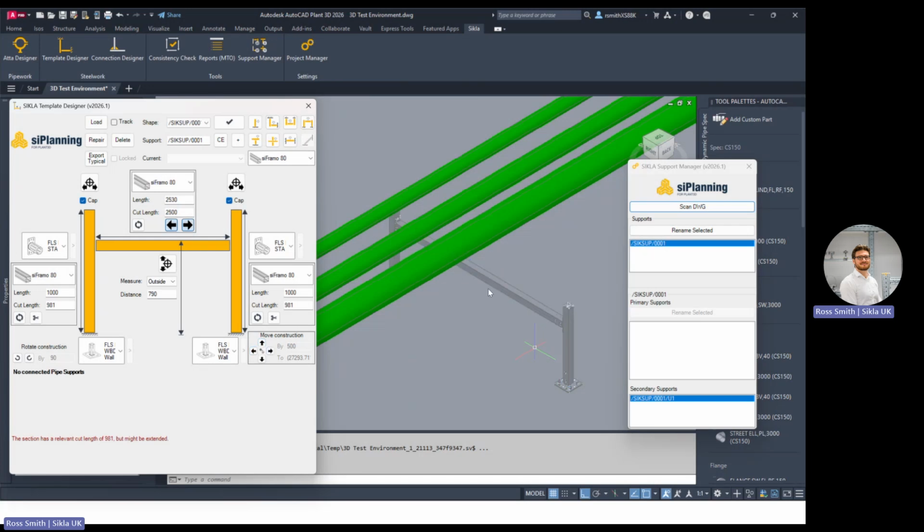I'm in solid view at the minute, a rendered view, and these are in fact arrows, these little things that pop out, but in a render view they look like cylinders. But let's move it this direction here. And when we have this tool, so I've left clicked on this arrow, by default 500 millimeters is the given standard move. You can see there's a silhouette popped up by how much this will move. If this isn't enough, you can manipulate this by just keying in another amount, and you can see it will move a little bit more. Let's go with 750, hit return, and our structure will move.